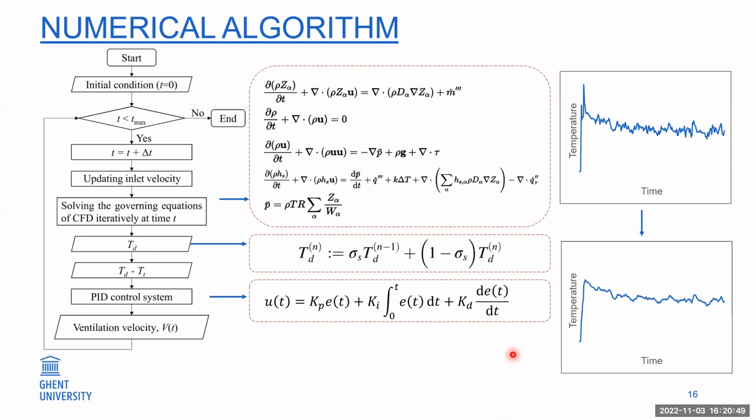So far, we have only designed this smart ventilation system conceptually. So we want to implement this method by simulation. In the simulation, we implemented it with the FDS source code. We coupled this PID controller algorithm into the FDS source code.